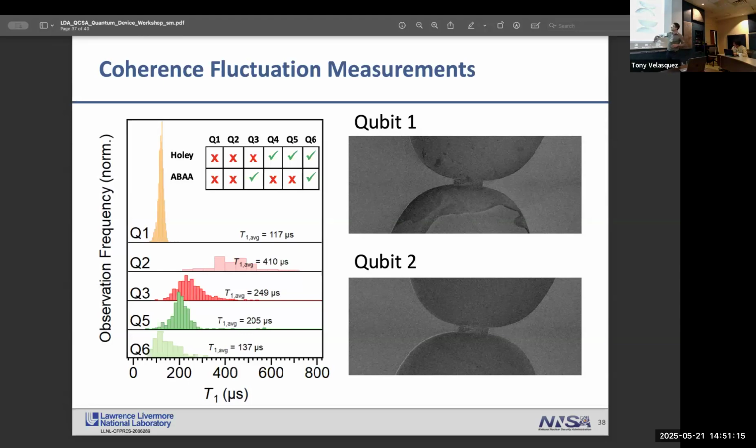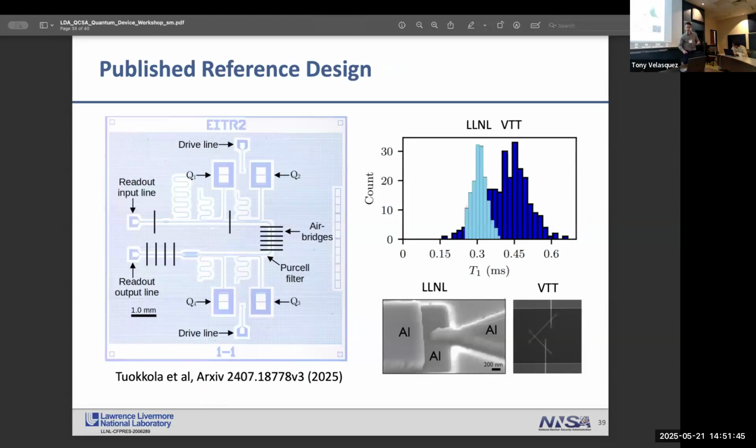As you can see, our best qubit has a T1 time of like 400 microseconds, which we're quite pleased at, and I'm advertising this because we hope that you can send your designs for us to make, and we can make you nice qubits using this process. And that's the average T1 time measured over a day for those who care.